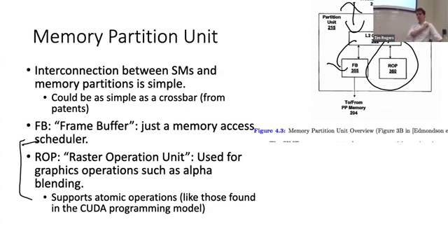Your SMs are just horsepower. They're just floating point machines. This is some dinky little thing that's out there just trying to mess with L2 cache lines. I mean, you could beef it up, but then do we want to put a whole SM out at the memory partition? Is that a good use of resources? It's a design decision.